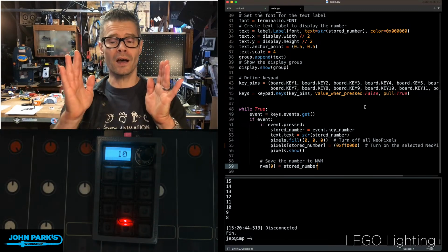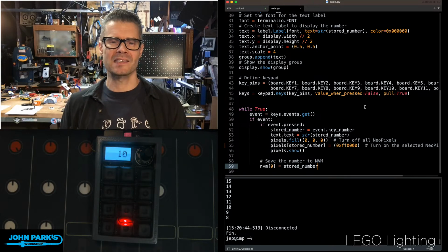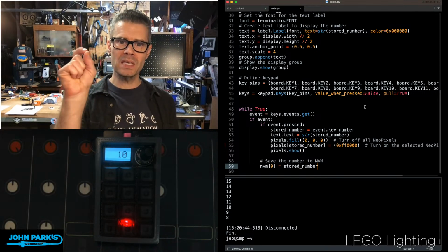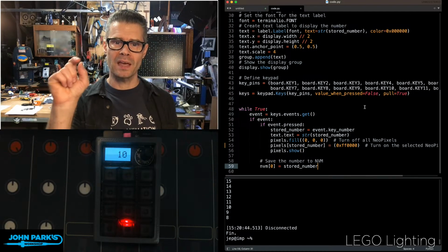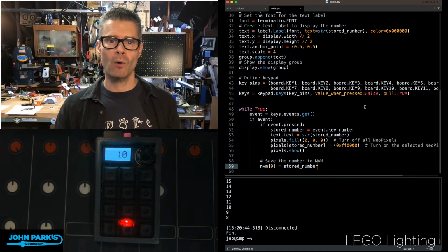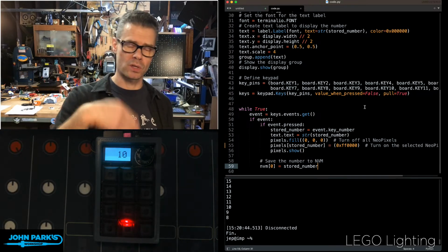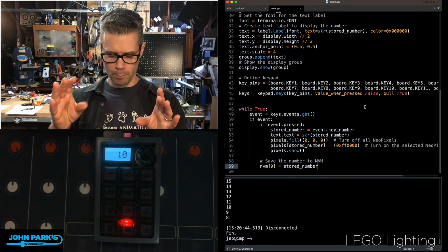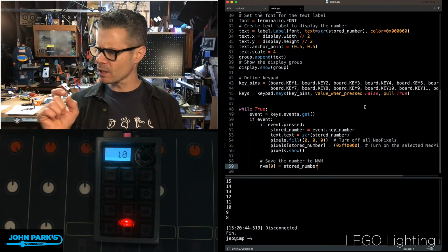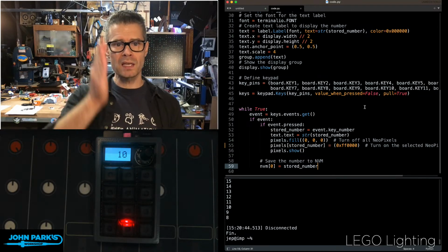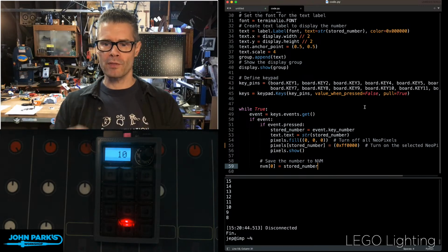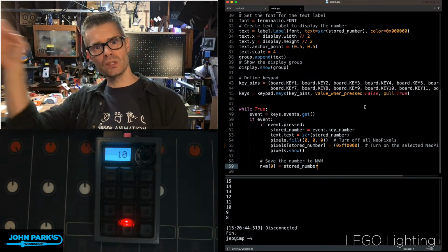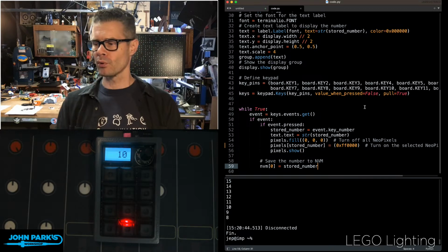Yeah, so the non-volatile memory is pretty cool because what it acts like is an EEPROM. Even though we don't have an EEPROM chip on these modern devices, it acts like a little piece of memory that can be written to, but it does not require power to keep that data in memory. So it survives power cycles, it survives resets. The block of memory it goes into is actually 8 kilobytes, I believe, on this device. And so we can write to all of those little positions, but rather than feeling like we're writing to a block and managing all that, we're able to just cast these values into individual positions in that memory and then pull that back.